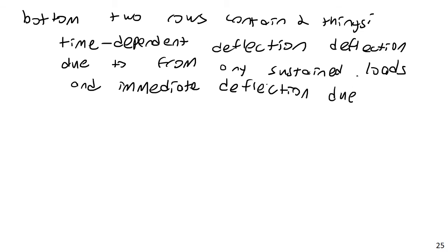So sustained loads would be things like dead loads, or drywall, brick, windows, etc. You're not usually going to be concerned with the long-term deflection of live loads, unless you have a heavy piece of equipment sitting in one place for a long period of time.